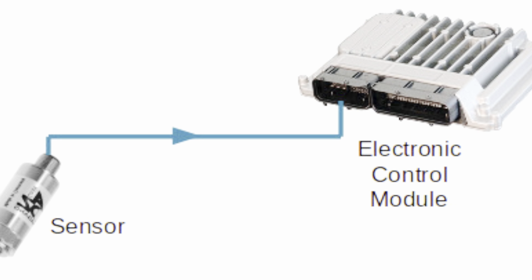Because of computer controls, sports models are coming out with the ability to take manual control of the transmission as though it were a stick shift, allowing the driver to select gears manually. This is accomplished on some cars by passing the shift lever through a special gate, then tapping it in one direction or the other in order to upshift or downshift at will. The computer monitors this activity to make sure that the driver does not select a gear that could overspeed the engine and damage it.